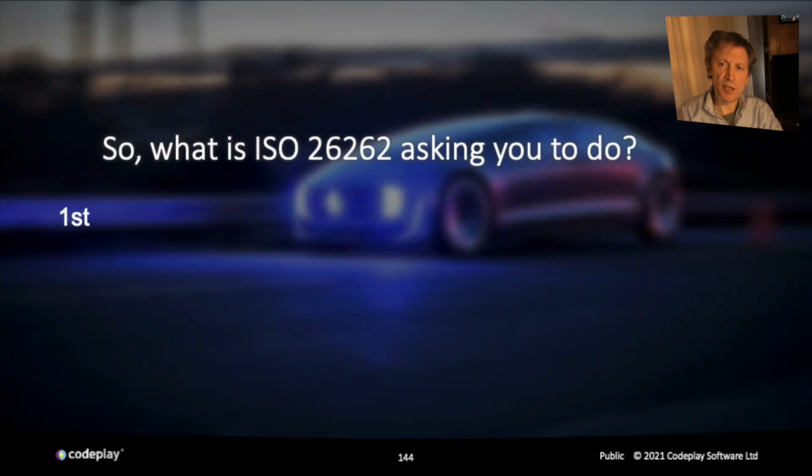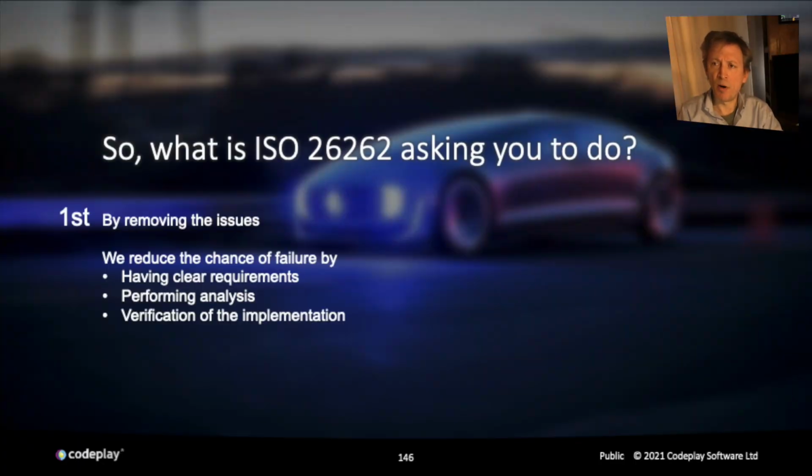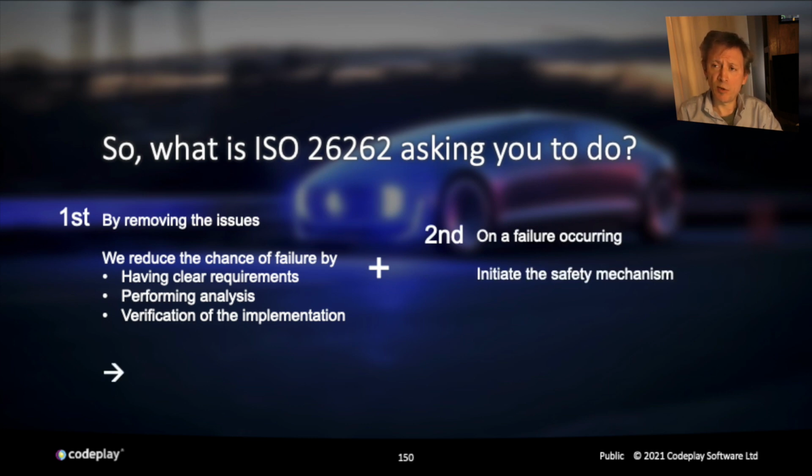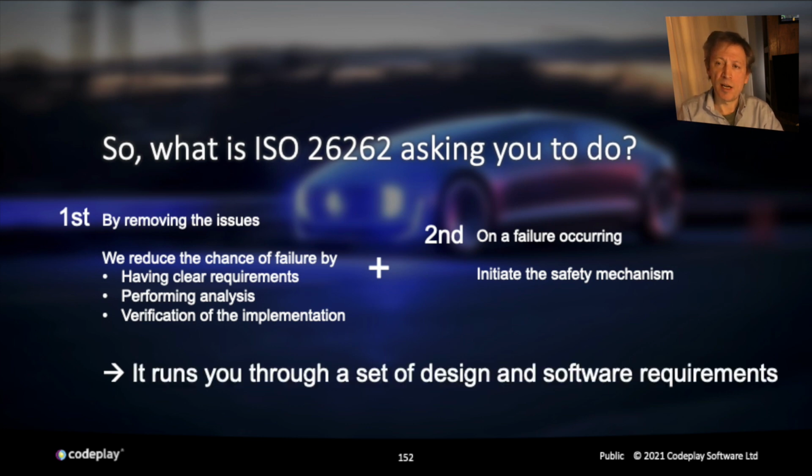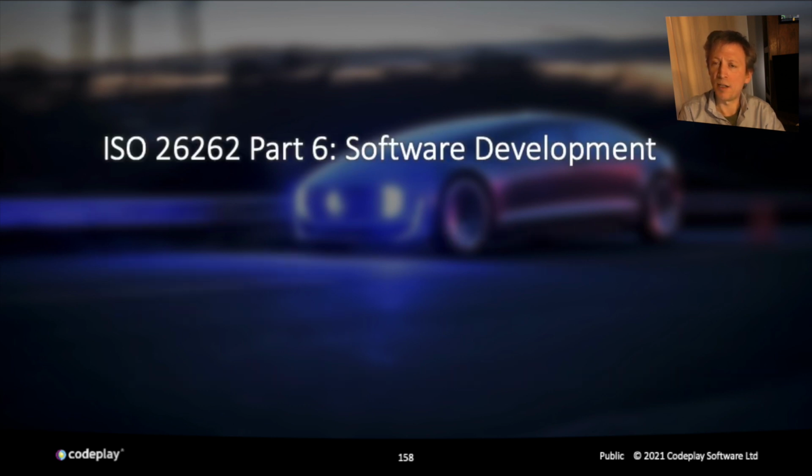ISO 26262 expects the analysis process to be part of the development of any system. And to ensure this, it's based on a quality management system. It operates as defined in either normal operation or, critically, reaching a deterministic safe operational state when a fault occurs. The same applies to software components of a system. The OEM determines the ASIL classification for a system and all the components inherit that classification. ISO 26262 expects a design to meet the requirements assigned to it for a particular ASIL classification.